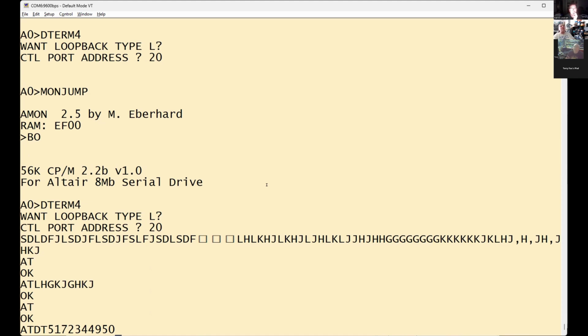Yeah, well, see, that's one of the things throwing me off, because all the other ROM images I load into the XG Pro software never show that 2 in the far left corner. Yeah, they're not actually Intel hex formatted files. The ones I downloaded from DRAM, it says there it's an Intel hex file. It's only an Intel hex file if it starts with a colon and a 0, a 1, or a 2. If it doesn't, it isn't actually Intel hex format.